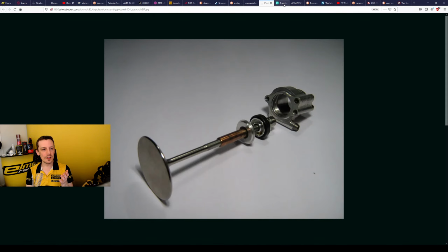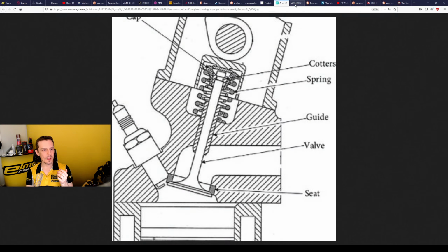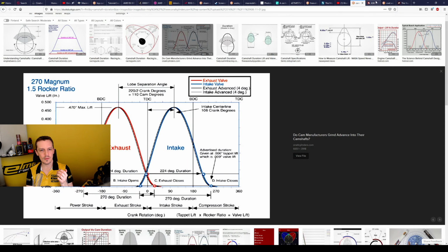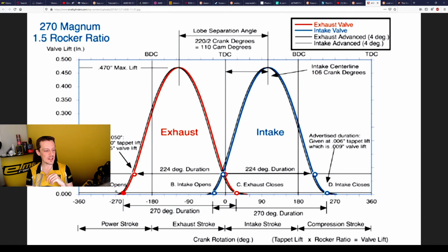You also need to see what kind of... so when you have a really quick acceleration on the valve, you still will have some kind of a shape like this. I mean, you can't have just a direct opening and then a flat area and then close it quickly, because parts have inertia, and if you're running those at high enough RPM, it's not really possible to do this type of direct opening thing that you hear the Koenigsegg guys and others talking about.